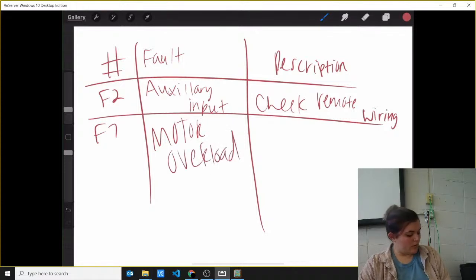So that would be your motor overload. And the description of that is an excessive motor load exists, reduced load, so drive output current does not exceed the current set by parameter P033. So see, that already refers back to the parameter you set. It's kind of telling you, hey, this motor is exceeding that parameter P033. So unless you want to keep getting this fault, you're either going to have to edit that parameter or set the motor to not produce as much.